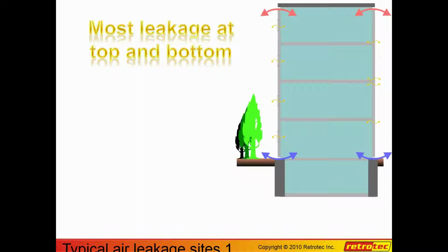That's not the only thing about finding leaks, but just some basics found over the years. Penetrations in the envelope also relate to windows and door frames and so on, where you've got a discontinuity. So when you're transitioning from a window into a wall section, those are the areas that we'll focus on, and all of you who've been in this business, I'm sure you know that.